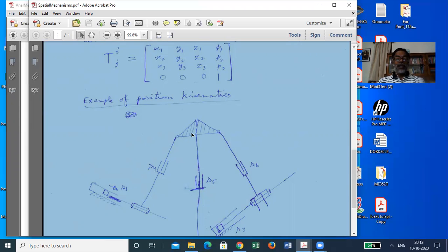And the loop closure is actually affected when we say that the same position and orientation of the platform that is used in describing this leg up to a point in the frame, and what is used in describing this leg up to one point in the frame, that basically is in a way loop closure. Because from a point on the frame here to this, and then from there to another point in the frame closes the loop.